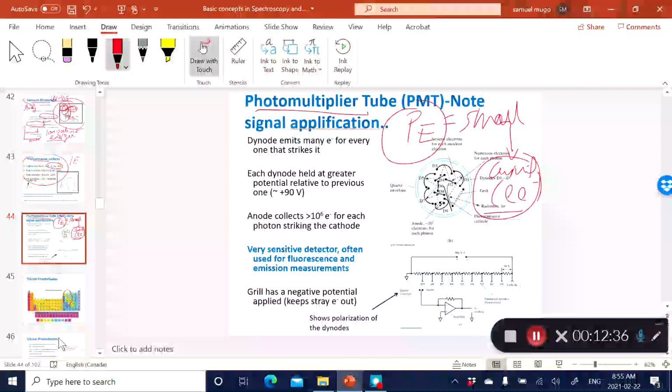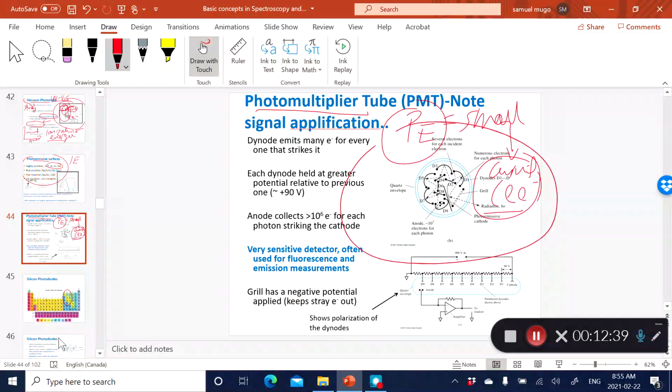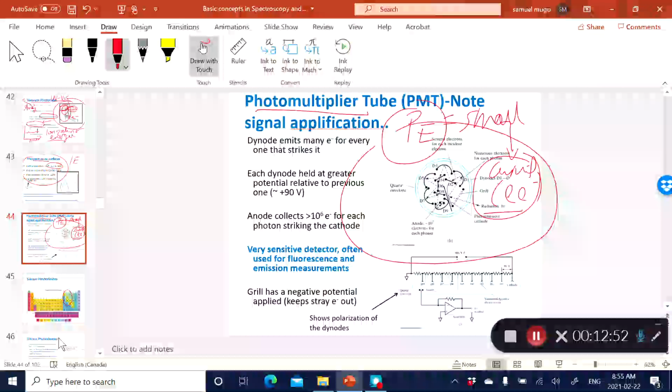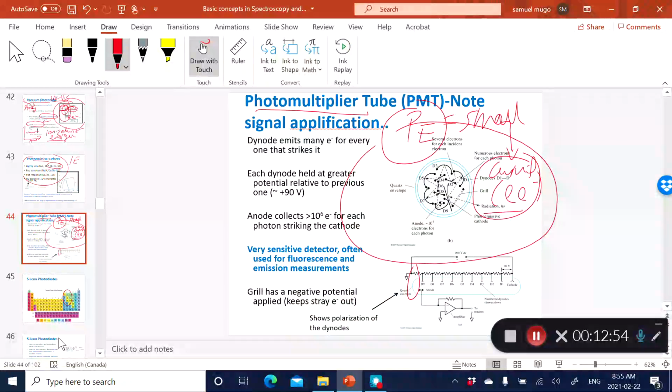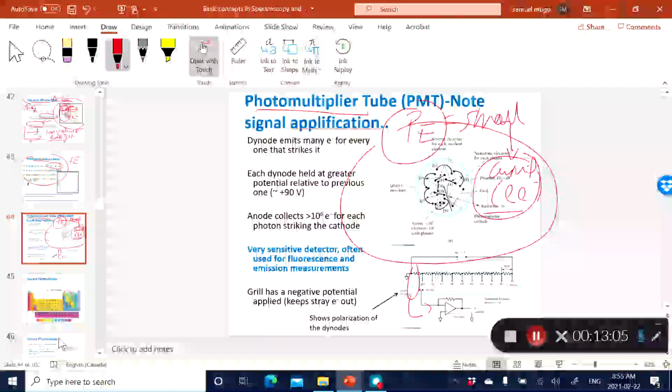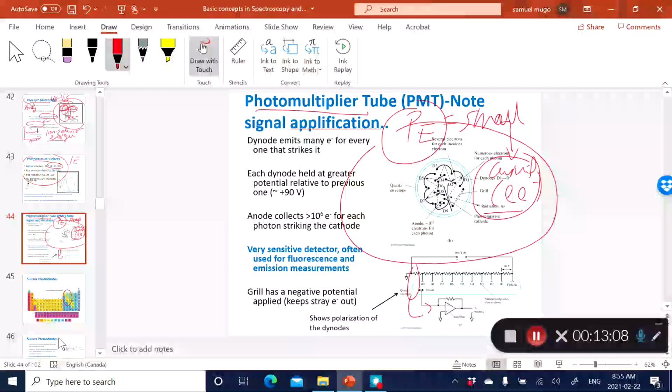Let me try to explain how it works, based on this figure that is here. Now, one vacuum phototube, often you're going to see some experts calling it a diode, okay? And the reason why sometimes they call it a diode is because it's connected to a power supply, often a DC power supply of a certain polarity. All right. So D refers to the vacuum phototube, which we already talked about, which essentially is just a cathode that is coated with a photoemissive material.